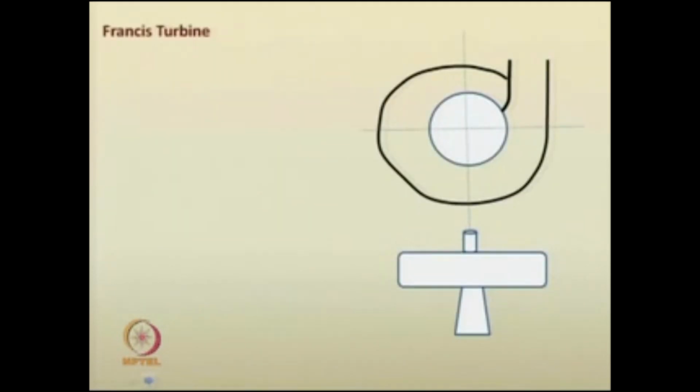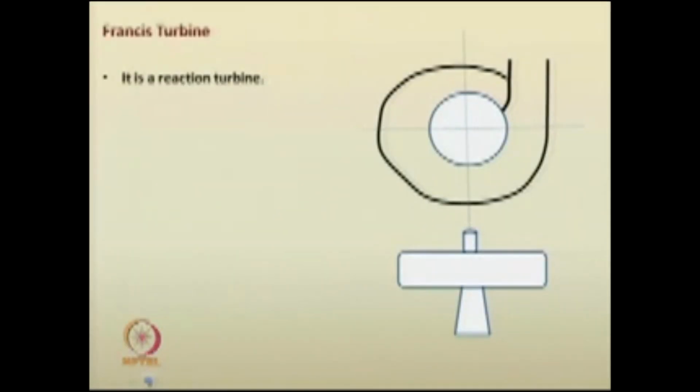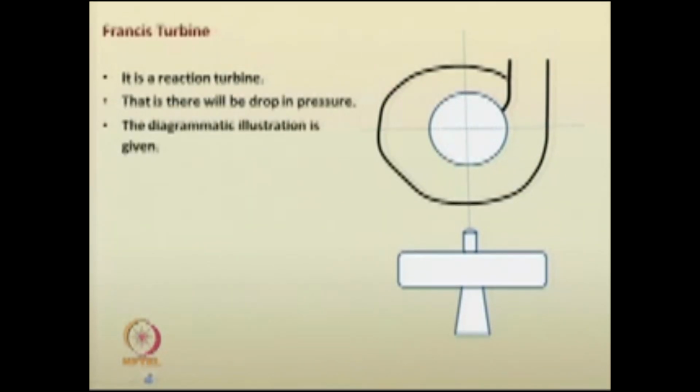Next, which we would like to deal with is the Francis turbine. What is meant by Francis turbine? Francis turbine is a type of reaction turbine. Now, you are quite aware of what is meant by a reaction turbine. Reaction turbines are the turbines in which the pressure is significantly changed from inlet to outlet, and based on that change in pressure, energy is delivered to the device. So, there is a drop in pressure.